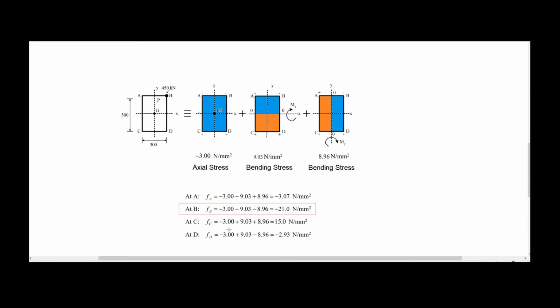So there's no doubt about this one. In the bending moment produced by the moment mx at the point B, this is exactly the point where we have applied the load. Compressive, the first one, no doubt. The second is compressive as well because the moment produces compression on top and tension at the bottom.